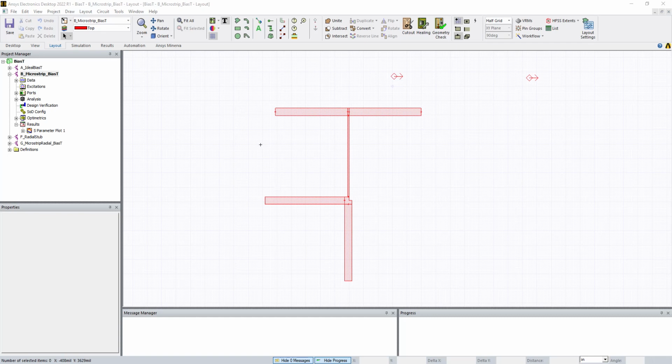So since there's no bottom layer defined, it assumes that you've drawn the negative, or that in fact the entire surface is the bottom layer. And same thing with the dielectric. The entire surface is the dielectric layer. So in this kind of Nexxim approach, it assumes that I'm just drawing the top layer. This goes back to what I was saying about the fact that you only need the top traces. The bottom traces are the ground. They're implied to be constant throughout, so you don't need to show them.